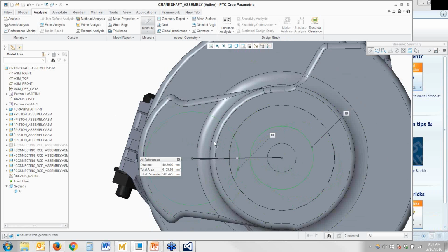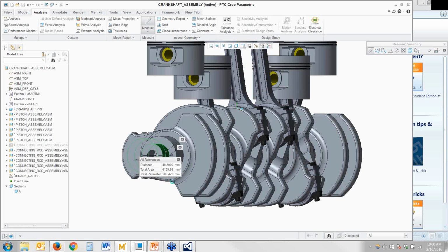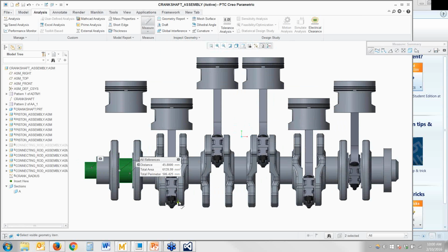there to the center of the other circle, that's basically the radius, or I guess half the distance that the piston travels. So in other words, the distance between those two centers gives you half the distance that this piston head travels vertically. And that is needed in our calculation. So we'll go ahead and save that as a parameter.